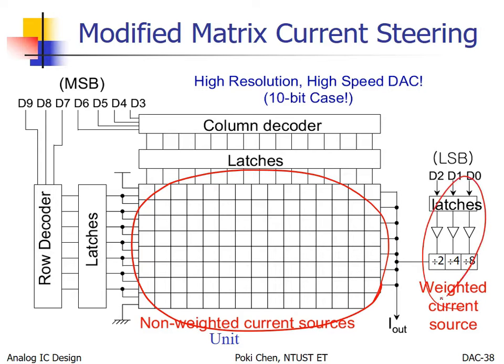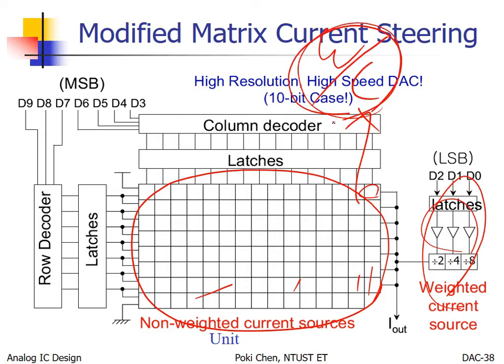And for them, usually, for many of the papers I read, usually we let it be. You design it from the beginning, you have 1 unit for all of them, and finally this divided by 2. So how to make it? For example, okay? For the current control bit, you have this. For the current control transistor, you make the final decision according to random mismatch. The aspect ratio for all of them is decided.